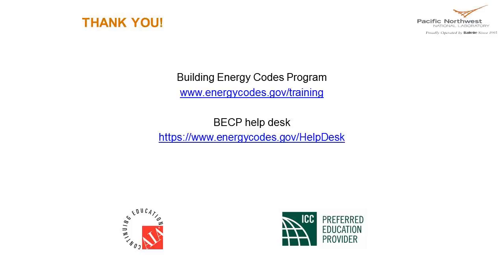Let's start with prescriptive, because UA trade-off is prescriptive. It's under the prescriptive provisions. And in 2015, there's an R value. You can show compliance based on the R value calculation, the R value method, the U factor method, or the total UA. REScheck is the total UA, by the way.